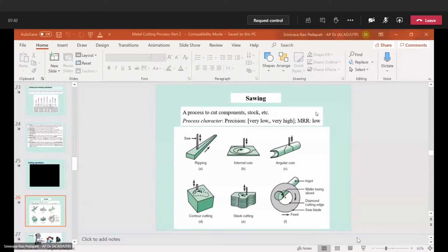Why? Because you answered correct, but you answered as per the textbook, like drilling. So you put a drilling tool and then drilling hole at some point, but it's not required in your component. It's wrong. And also you should show it on your component, where it is drilling, how it is performed on that component. So with reference to your component, you should identify the operations that are performed.